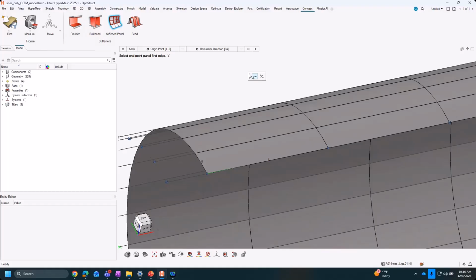Okay. You want to make sure you remember this, because this kind of burned me when I was practicing this. You define the edge densities and the beams on the frames and the stringers independently of each other. So what do I mean by that? Let's take a look. Let's say I want 3 rows of quads and beams along these edges of my panels. So I'm going to click on that edge, go to 3, and then this little option here gives us our option to define our beams.